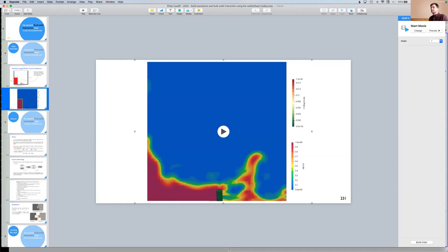So it's in the interFoam or interFluid class, the only extra thing we have to define is what the traction, or the force, is on a given patch. So for that specific fluid model, its definition of force, we need that to be able to use FSI.